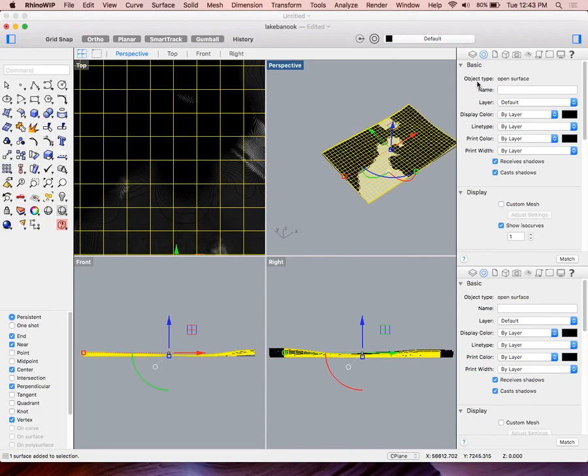They're different on each platform, but just go into properties on Windows, or I guess this is the properties panel on Mac. And it will also say it at the bottom here on the left-hand corner. It will say, obviously, your last command, but it'll also say if that was a successful command into a closed poly surface, or if it's still an open poly surface.